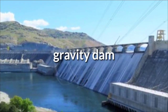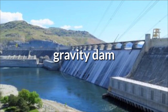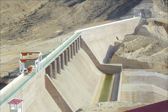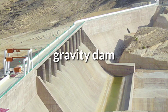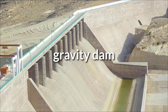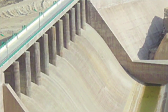New masonry dams of both gravity and arch designs are being built in India, China and other lands where the cost of labor is low. It is adopted overall to prevent sliding and contact with the foundations, and the foundation itself must have appreciable shear strength. In carrying out the stability calculations for the many proposed sections of the dam, the uplift must be taken into account.